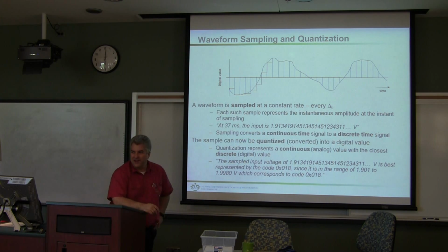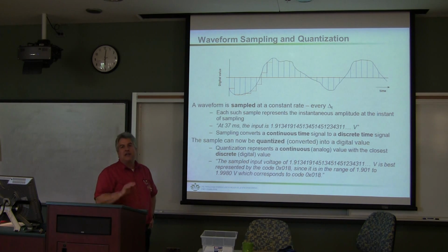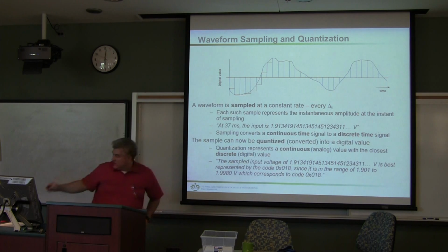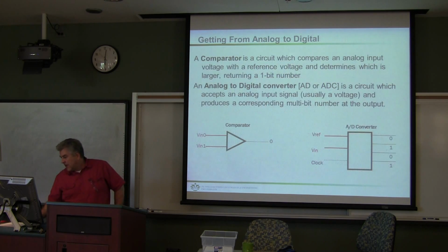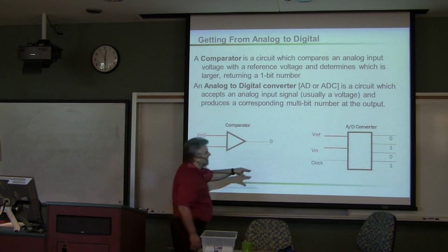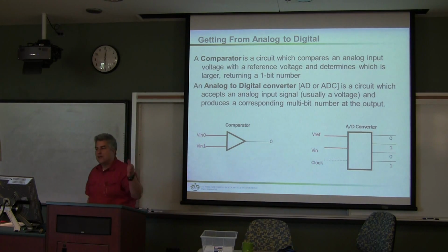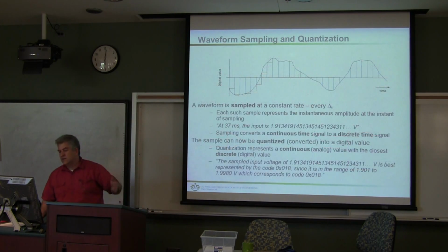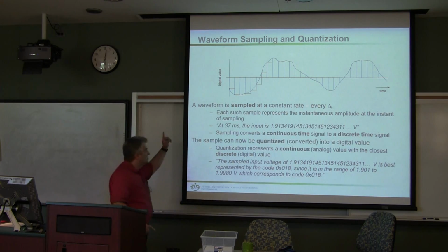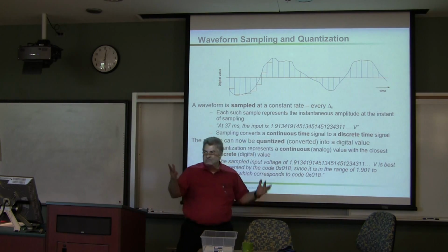You have to find the quantity of. And typically it's a signal that's continually changing. So if you're converting it to the digital world, you actually have to sample it at a certain frequency. So in the earlier slide, I showed something called a clock. That's because the clock is used to say, all right, at this time measure, now this time measure, now this time measure. So it's going to be continually changing in most cases.